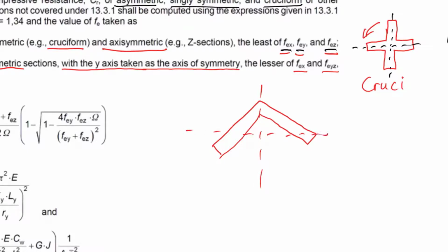with the y-axis as the axis of symmetry. Now, to be perfectly honest, I get very confused when I start running these calculations, because in the red book, for instance, you will have this is your y-axis and this is your x-axis. Now you rotate it, and now your y-axis is there. And now you've got two y-axes, and then it's very easy to make mistakes. So what I suggest to students is call this y-primed. Just call it something different.